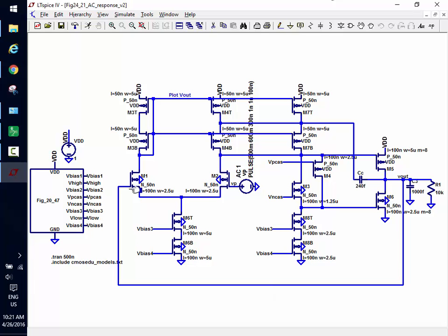Yeah, so it can go to VGS plus 2 VDS SAT, which is roughly about 450, close enough, right? So that's not going to get you to 80% of VDD. Does everybody see that? But if I go the other way, how far up can I go?